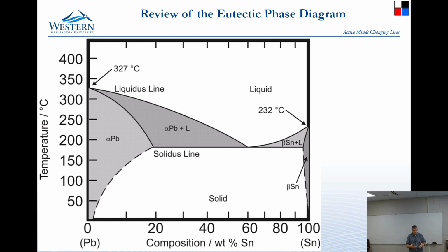So it is a different substance composed of the constituents. If you look at it, it will look like one material because the lead and the tin are bonded together there. It looks like a continuous material throughout this region. When you get into this area over here, you have more tin than is able to stay in solution. So you have little globs of tin floating around in it, as well as the solution. But remember, this is solid.